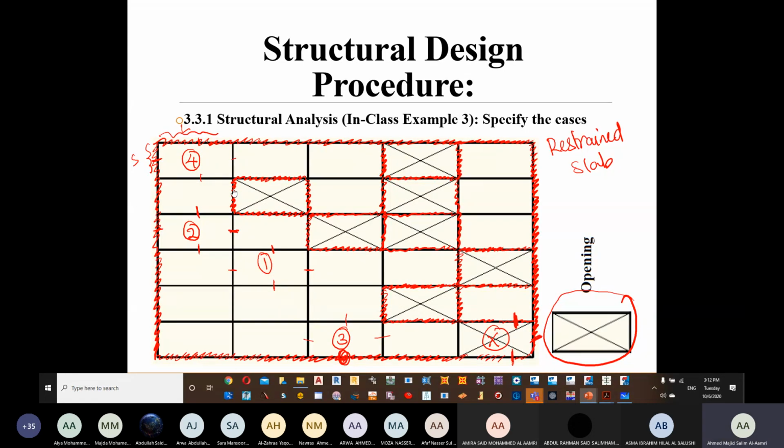So it does not fit. If I take another one here, this is one discontinuous, another discontinuous, a third discontinuous, it does not fit. So not always. In a typical building, yes. Here, one short, one long, then we have one continuous, one continuous. Are we clear? Two adjacent edges discontinuous means one long, one short.